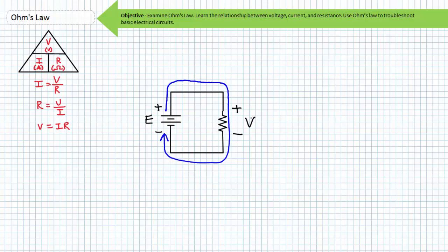In this case, our single element will have a voltage drop equal in magnitude to that supplied by our source. With only one element in a complete circuit, it may seem painfully obvious that every voltage rise is accompanied by an equal and opposite voltage drop. We'll return to a more thorough analysis of this when we cover Kirchhoff's voltage law in series DC circuits. It seems simple and inconsequential, but it isn't, and Kirchhoff's voltage law serves as an extremely powerful and often misunderstood means of circuit analysis.